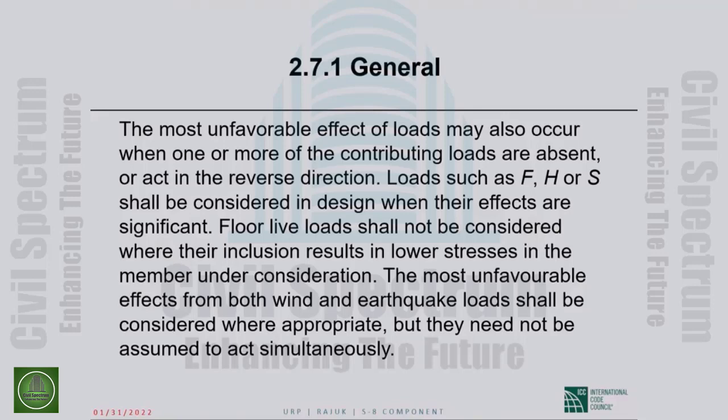Otherwise, you get floor live loads shall not be considered where their inclusion results in lower stresses in the member under consideration. Okay, if live load not being present is more critical, that's what you should consider. And live loads may or may not be there. If it's not being there is more critical, that's what you should consider as basis of design.